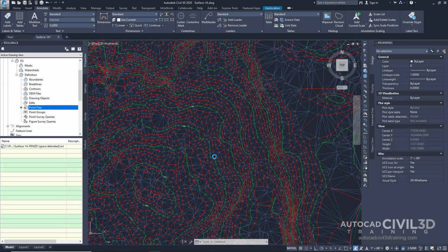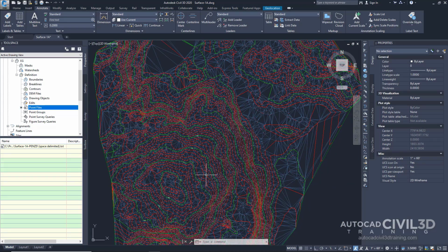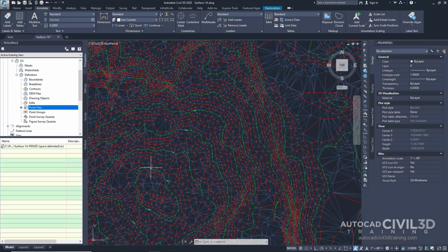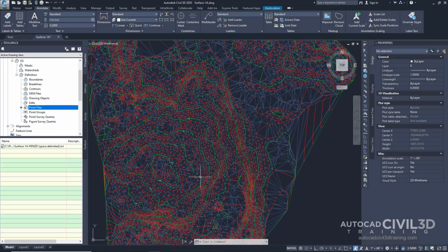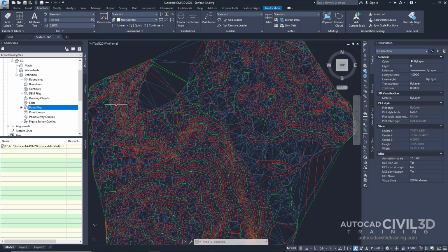So what they did is they probably used a drone with LiDAR, and what LiDAR does is it actually creates all of these points as it's flying over it. So you can get a drone to go out and go just back and forth across the site and collect all of these different points as it's flying around.